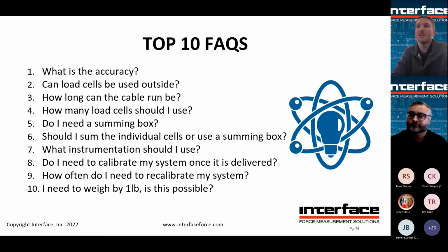Do I need to calibrate my scale once it is delivered? It is strongly recommended. For some scale systems we can offer factory calibration, but who knows what happens between here and there. How often do I need to recalibrate my system? Again, it depends. How often do you use your scale? How important are the values to you? You could do bi-weekly, once a year, but quarterly is probably most common. Also, not a bad idea, if possible in your scale system, is to purchase a verification test weight. Every morning, just throw that weight on there and see if you need a service company to come out.